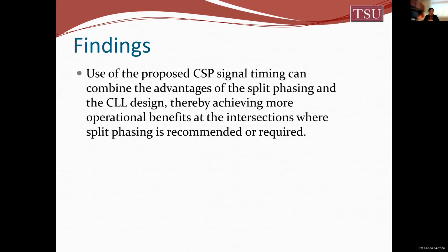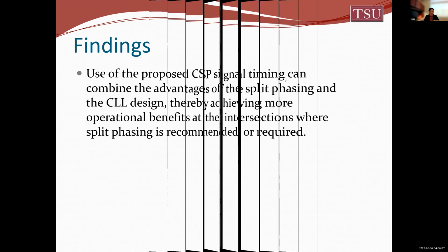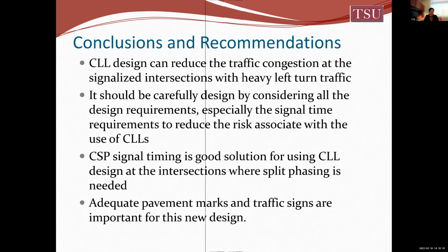So this is the major finding. Using the proposed CSP signal timing can combine the advantages of split phasing and the CLL design. Therefore, it achieves more operational benefits at the intersections where split phasing is required or recommended. So this is our major finding for the second study.